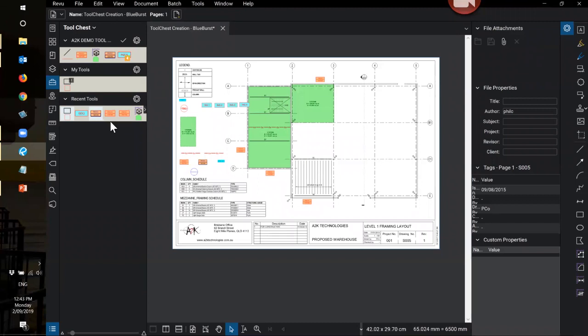So you can send your toolsets that you have created as an email attachment, for example, as a BTX file that can be double-clicked, and it will automatically import in the computer, or it can be done through the Manage Toolsets dialog box. If the users will be sharing standardized toolsets, you can link its location to a network location to which they have adequate folder permission as well.